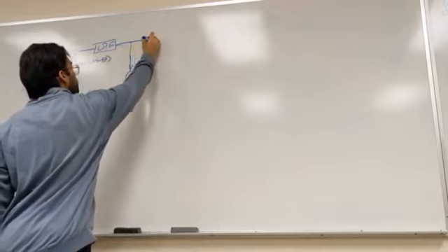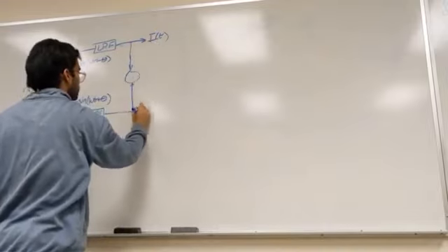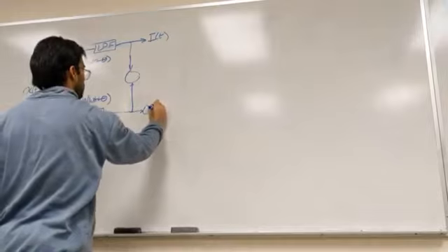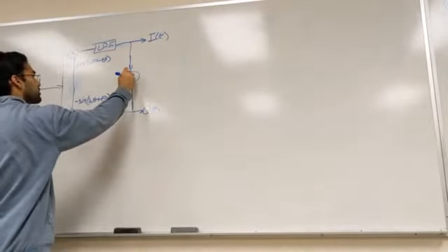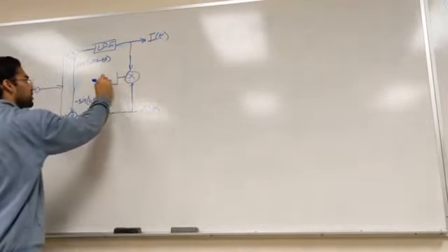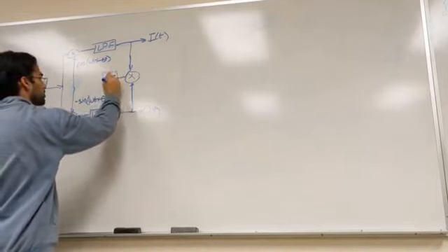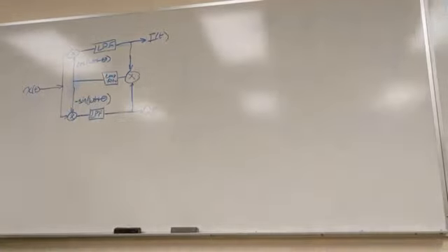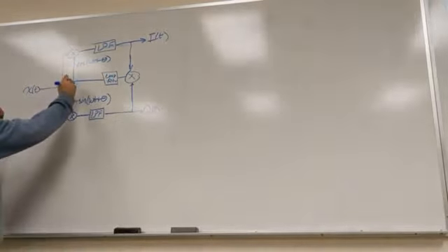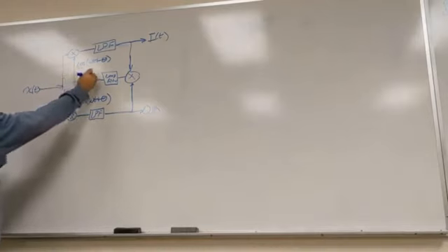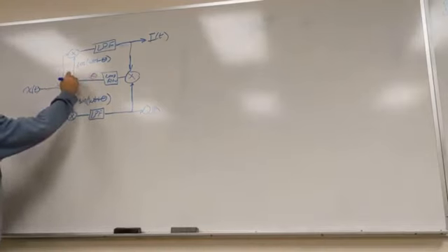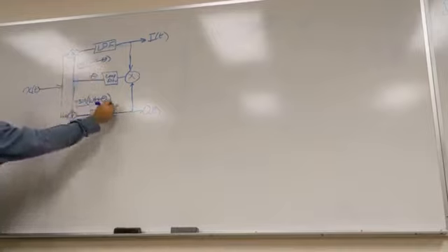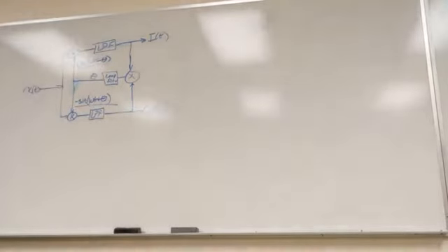Keep in mind, here is your in-phase. Here's your quadrature. And knowing this, you can pass it through a loop filter. And then it goes here, where you just say this is your output data, and you pass data into these modules, the sine and cosine. And this is a Costas loop.